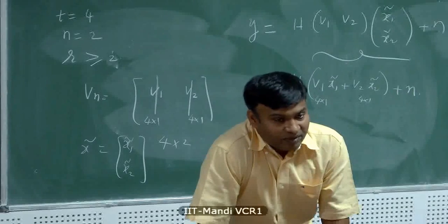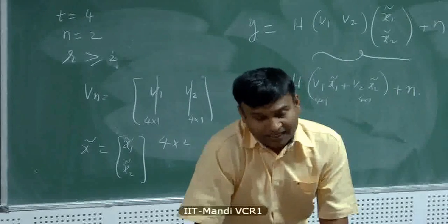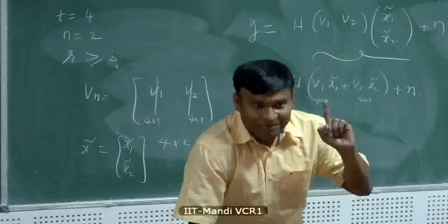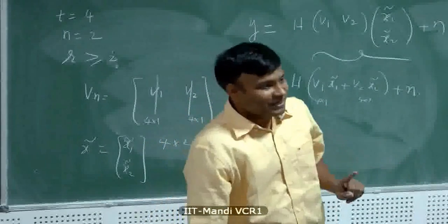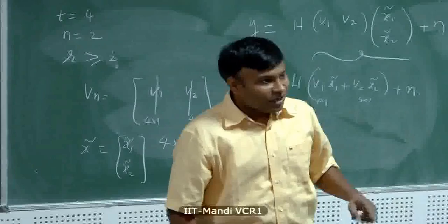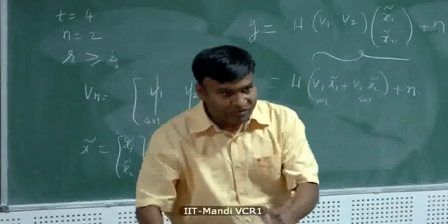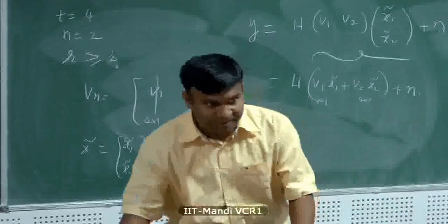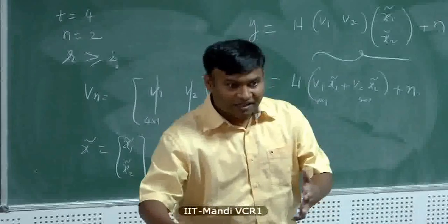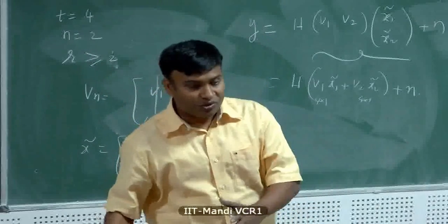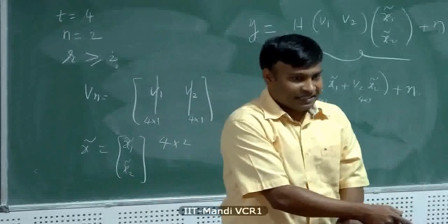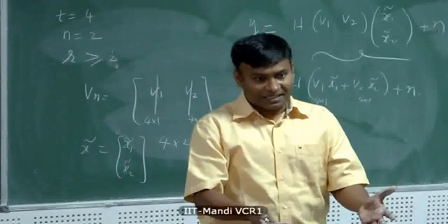But then you may be wondering, why is that optimum? Well, I think you should have done spatial multiplexing, because when you have so many receive antennas and so many transmit antennas, the better thing to do is not to form strong sharp beams, which only give you an array gain, which is an SNR advantage, and log of 1 plus SNR can only take you so far because the SNR is inside the log. What you should do is get a pre-log multiplicative factor, which is the spatial multiplexing gain.